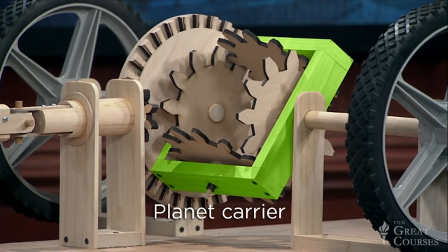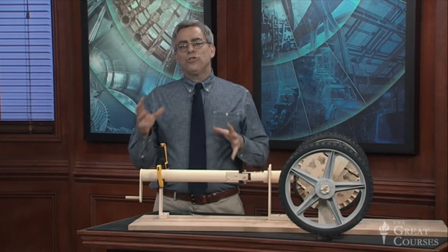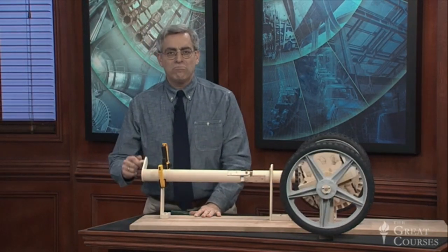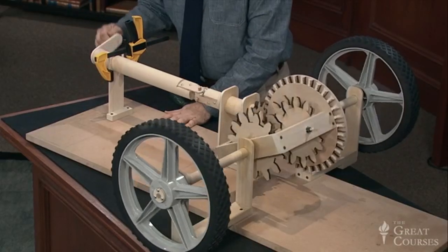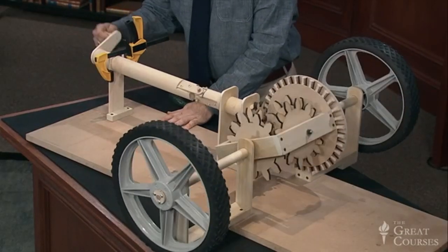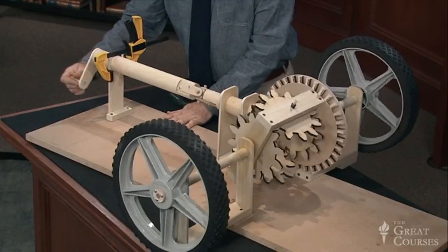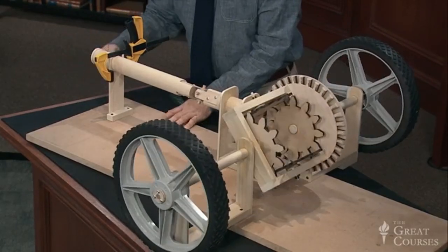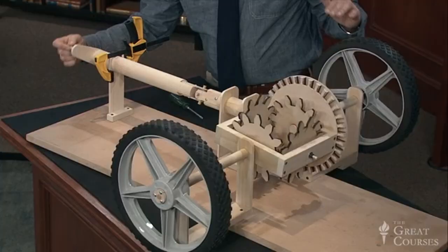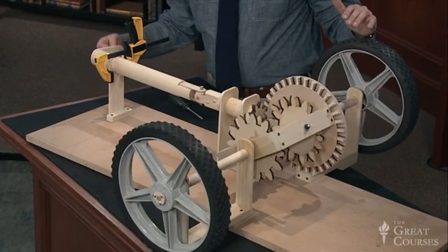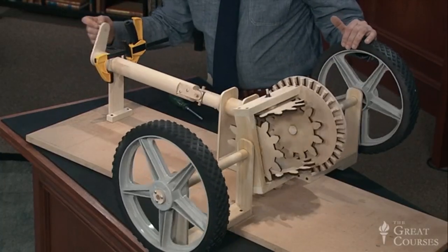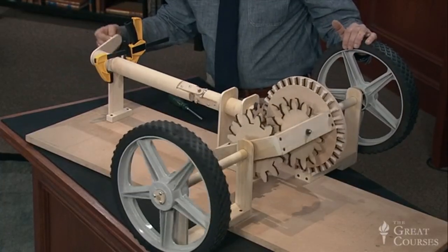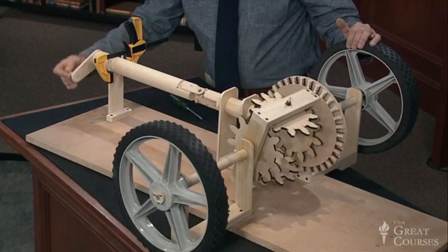of the axle shafts. So now when the vehicle's driving straight ahead, this entire planetary gear set is basically just going along for the ride. The planet gears don't rotate, and the sun gears and axles are spinning at the same rotational speed as the crown gear. But when the vehicle turns, the 2 drive wheels will rotate at different speeds. And as a result, the planet gears rotate to accommodate the different shaft speeds, like this.